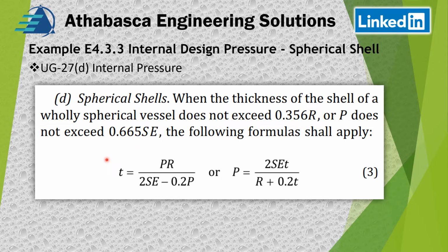The example doesn't really get into that, and it should. You can use this equation to calculate your thickness, and once you determine your thickness and add your closest nominal size, then with your minimum thickness, you can calculate your maximum allowable working pressure for the sphere components.